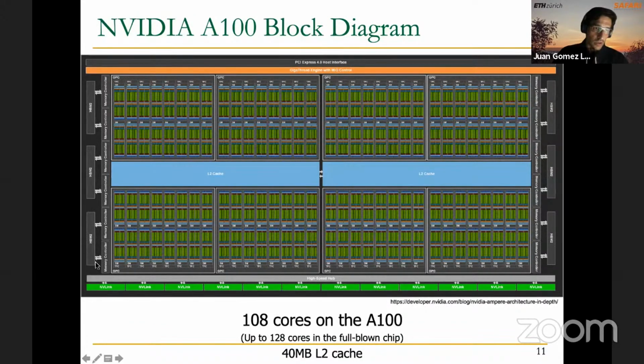These are 3 of these HBM2 stacks, and here we have another 3. As you can see, we access each of them via 2 memory controllers. And here in the middle, you can find the whole array of GPU cores that access these HBM stacks using the memory controllers.